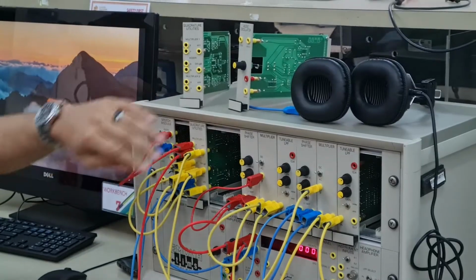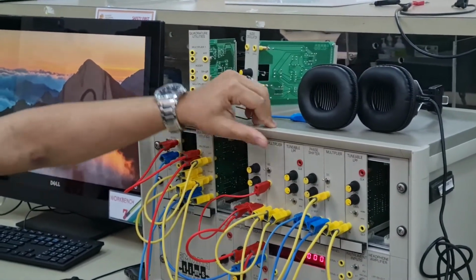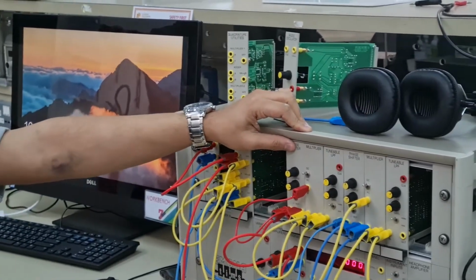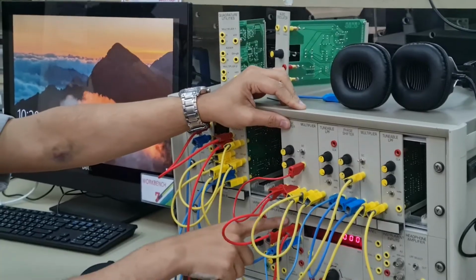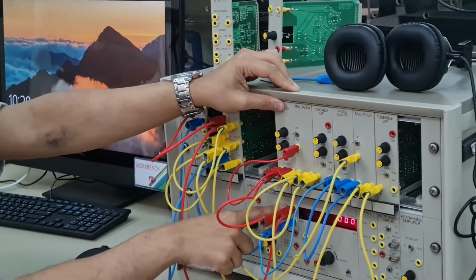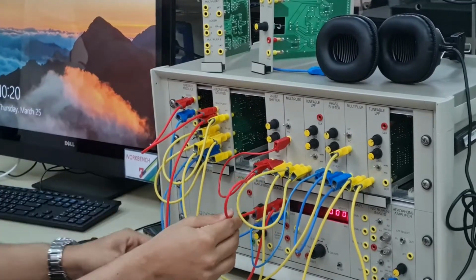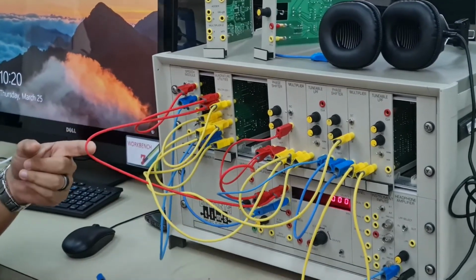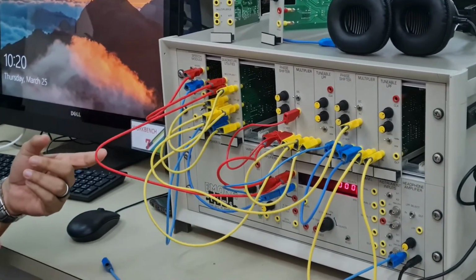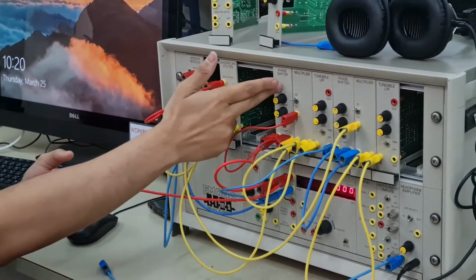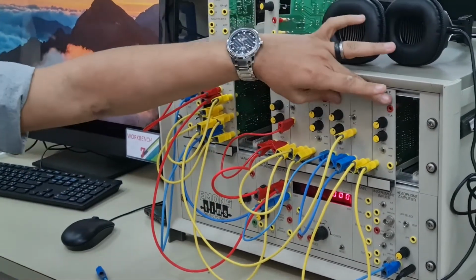Then on the receiver side, I have two demodulators, each with a multiplier, a low pass filter, and a phase shifter to correct the phase. Even if the signal is coming from the same source, because of the wire, they can have different phase shifts, because wire means traveling. When the signal is traveling, there might be a phase difference between them. So we'll correct it with the phase shifter, and the same thing happens for the second signal.